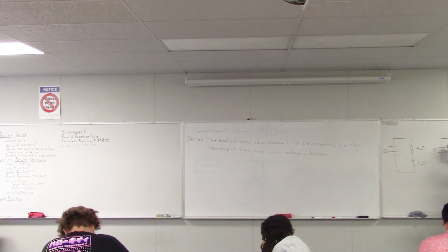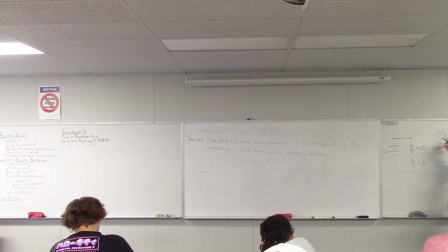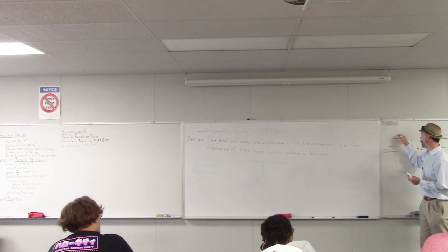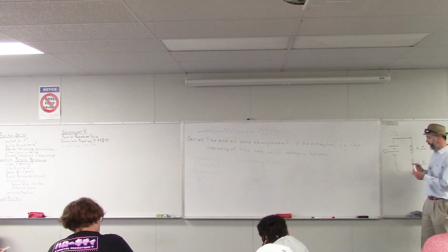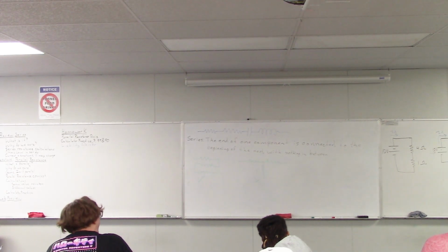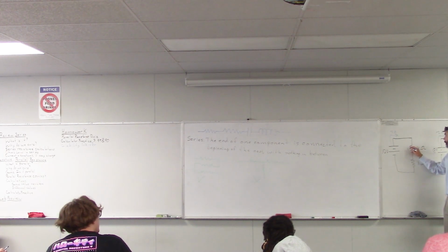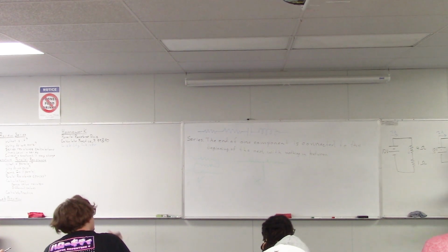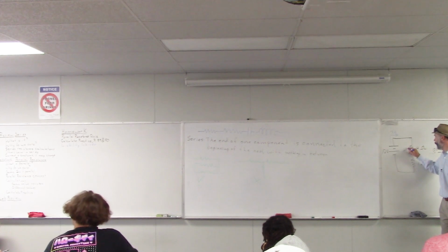So that's the amount of current flowing right there. And since these two circuits are equivalent, if we have 2 amps flowing out of the power supply in this circuit, that means we also have 2 amps flowing out of the power supply in that circuit. Okay? And that 2 amps flows around, and how much of it goes through this first resistor? 2 amps. Exactly. All of it, 2 amps, because it has nowhere else to go.